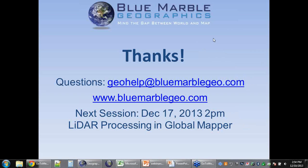It doesn't have to be EPSG. It could be from like a PRJ file. It could be something you manually entered. All of those custom parameters or EPSG downloaded parameters are going to go into your custom data file. So that's going to be the custom database that accompanies the main geodata.xml file. So that will be treated as a customized system, and very likely anything that is brought down from the EPSG will be added to the next release of the software. We periodically synchronize with the EPSG database, but they are all handled as custom entities in your local database.